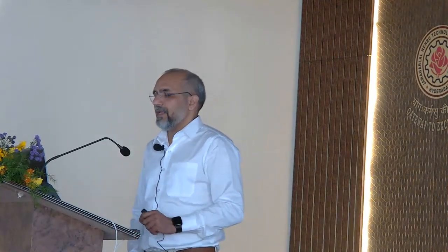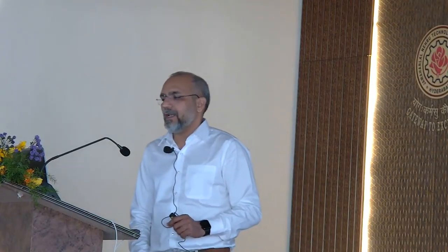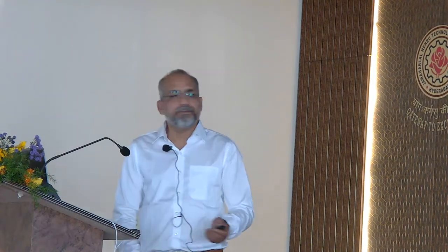And here, this is one example of the high density plasma enhanced chemical vapor deposition method. It basically has two power sources: one may be capacitively coupled plasma, or the second is inductively coupled plasma. You can use either of these sources to create the plasma, and then you will have a high density of plasma to enhance your chemical vapor deposition process.